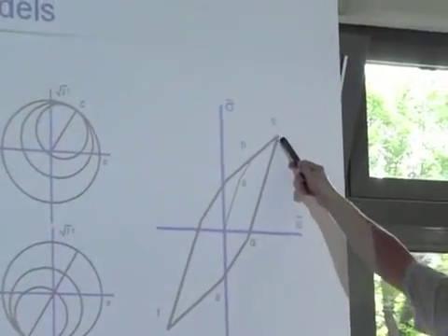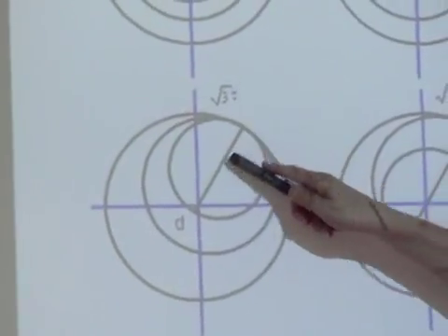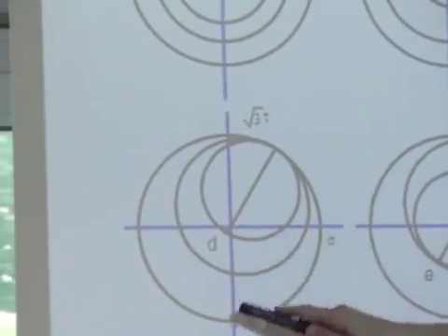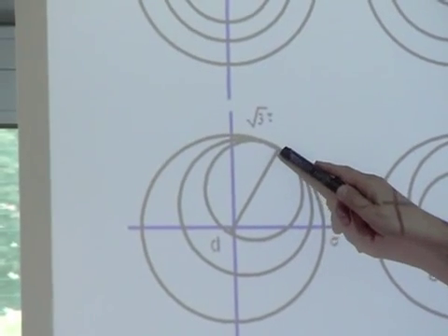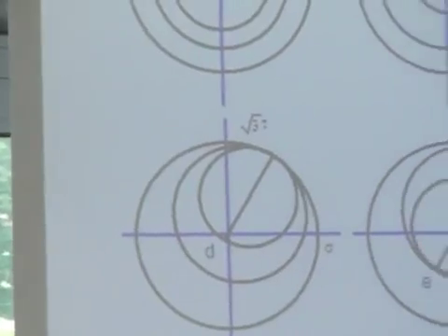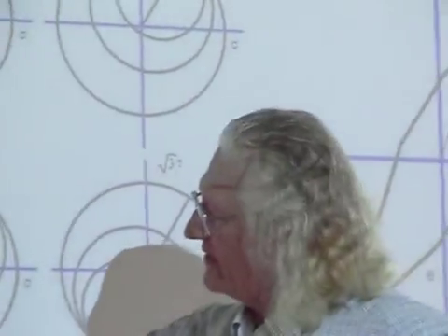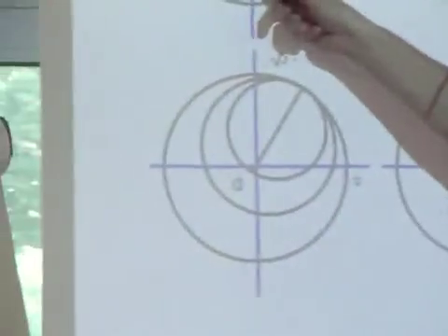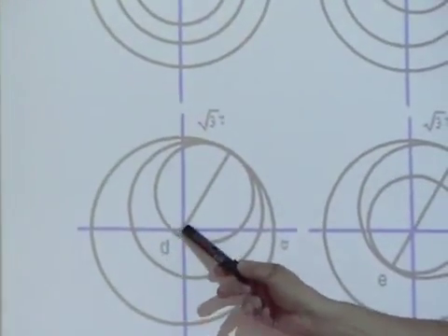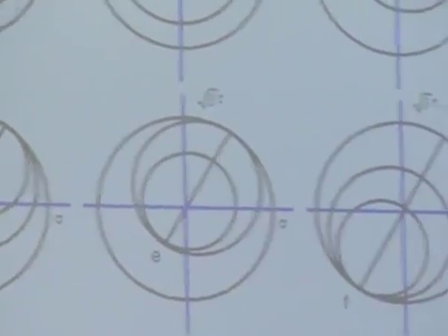So now I'm sitting at this point C, and now I'm going to unload it. And I'm going to unload it along this path in the reverse direction. And you can see I dragged all of these surfaces in one direction, so when I unload it, the elastic range is doubled. And so I get double the elastic range out of it. But not only has the elastic range doubled, so has this range between the first and second surface. And so then I traverse across this way, and that gives me this.